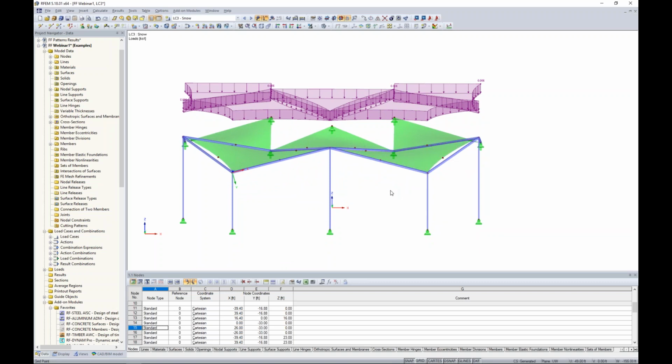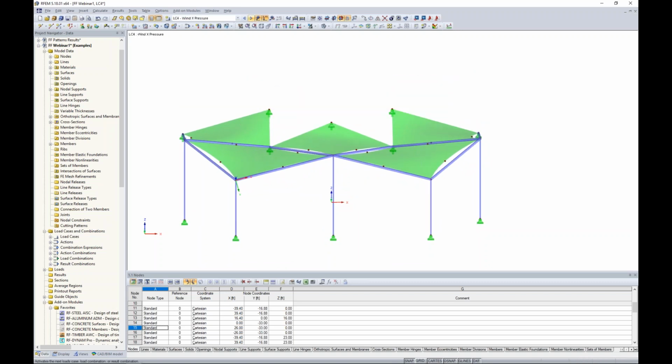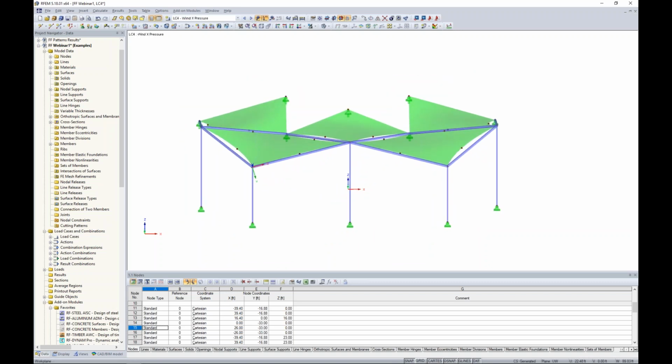higher snow loads there. So that's the advantage of a projected load. When it comes to our wind loads, according to the ASCE 7, Table 30.11-1, this does address wind loads on attached canopies. So for time's sake, we don't have time to get into this today, but I just want to